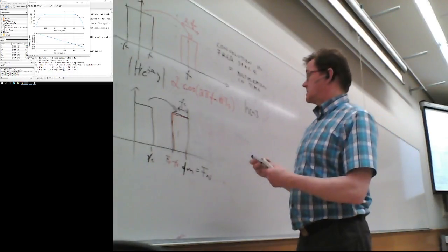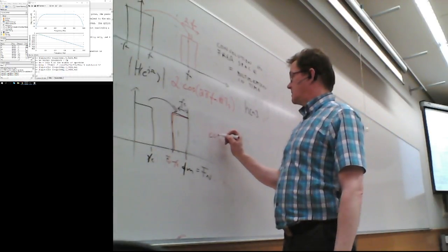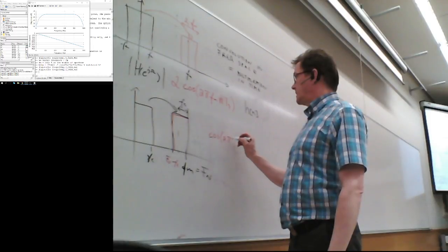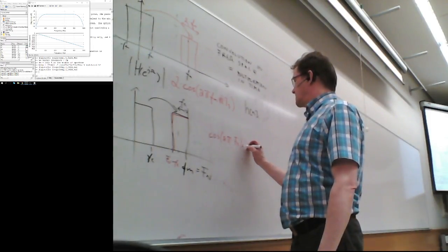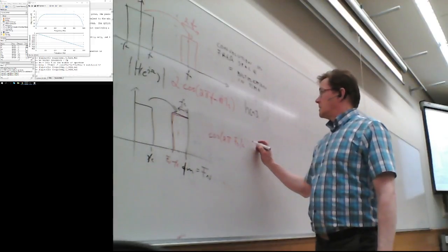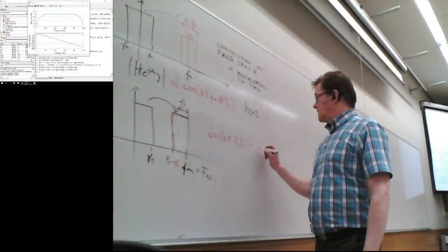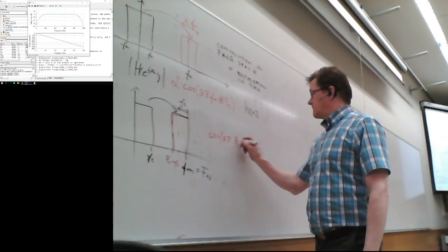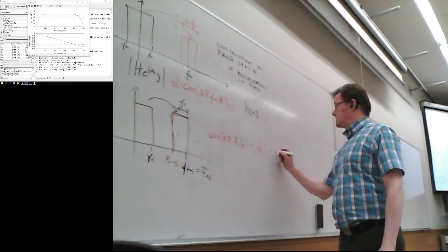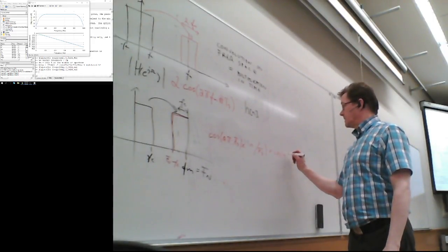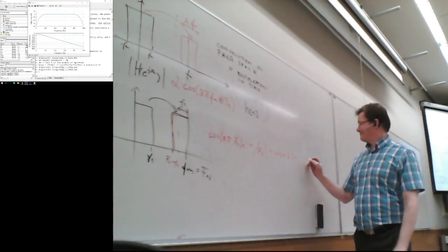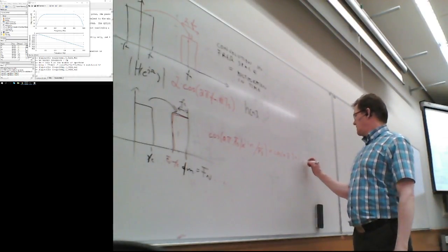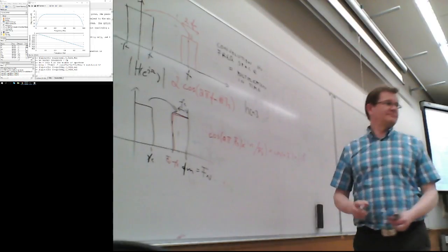But anyways, now we have cosine of 2 pi. All right, so let's see. Cosine of 2 pi times Nyquist rate, which is Fs over 2, times n divided by Fs. Okay, Fs cancels like that, which is cosine of n times pi, which is actually minus 1 to the power of n.